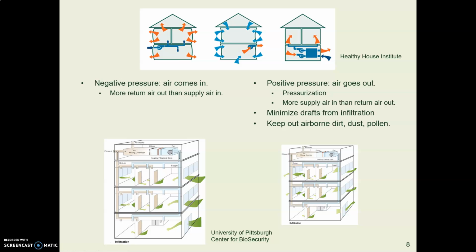We were talking about supply air and return air and needing to keep the air moving. And part of that is the idea that when you're blowing air into a room, you may be just slightly increasing the pressure in that room. Depending on what your building occupancy is used for, you might want to have your room pressurized so that you don't let outside stuff in.